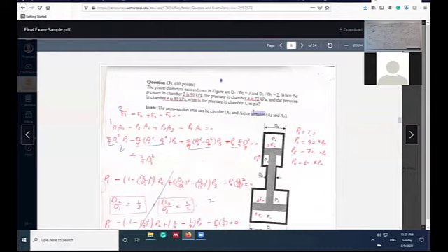3 are annulus. For example, if you want the area here, it's pi over 4 times D2 squared minus D1 squared. The same for area 2, it's D1 squared minus D2 squared. And of course, pi over 4. I give you the diameter ratio, divide by pi over 4 D1 squared. You will see everything is simplified like this.